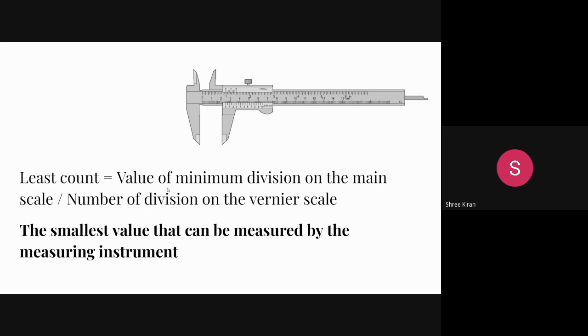So in order to check all this, we should calibrate them, to check whether the wheel has worn by checking the dimensions. We must know, for a new grinding wheel, what will be the dimension of the teeth, the depth of the teeth, the angle of the teeth, the diameter of the wheel, everything we will be knowing, right? So after the usage, what happens?